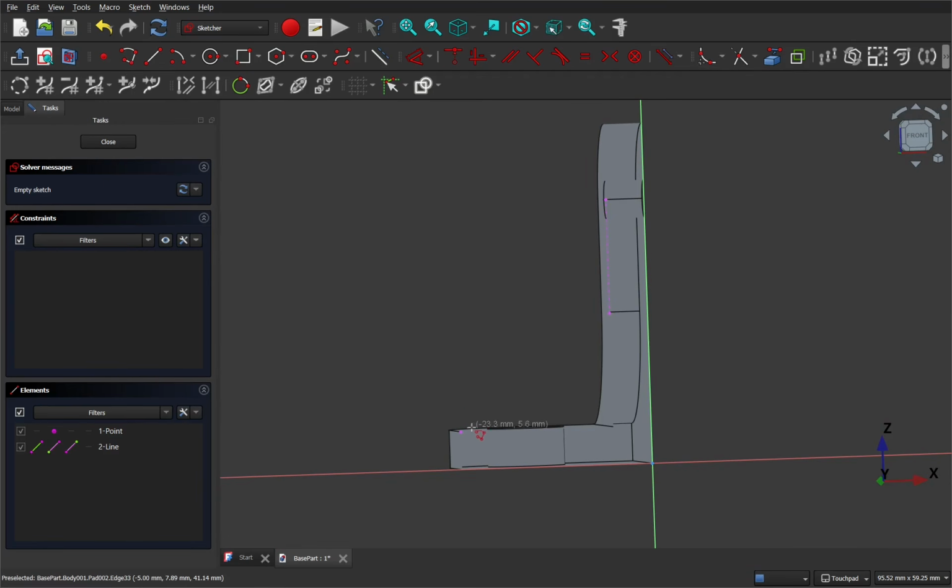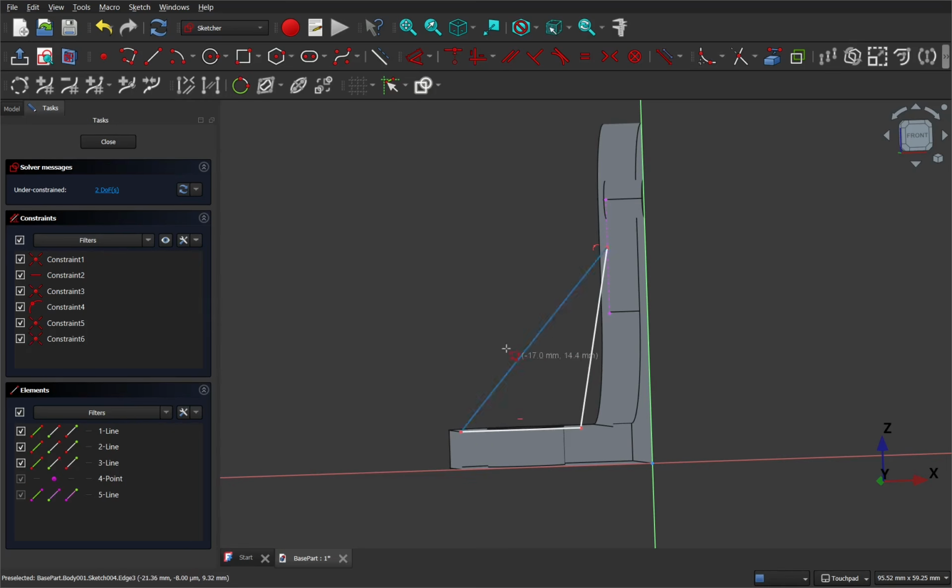And we'll attach to this point, which is coincident. Now, if I had the line in, say, here, and the point is here, I can come up and attach my top part of the line to this line here with point on object constraint, point on object, and then close the geometry by coming in and attaching back the starting point of the polyline.